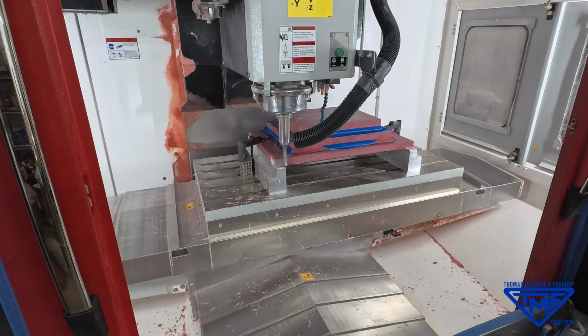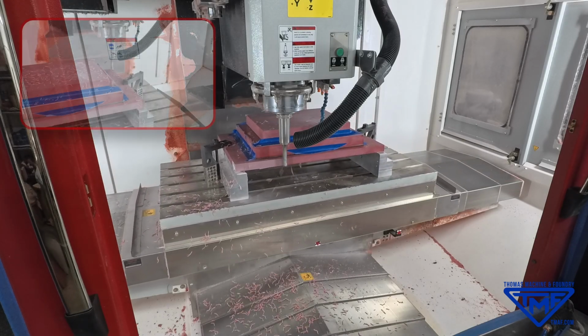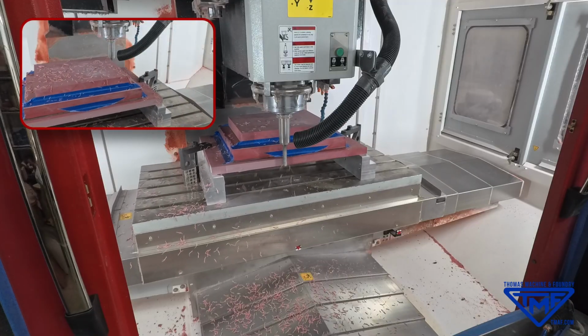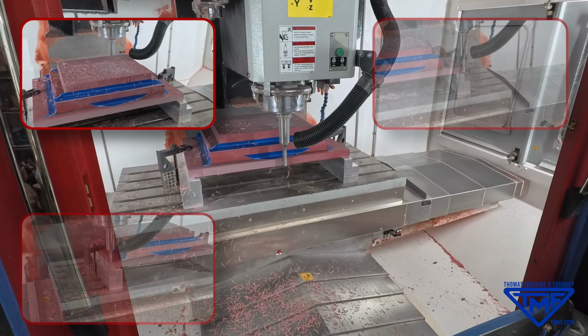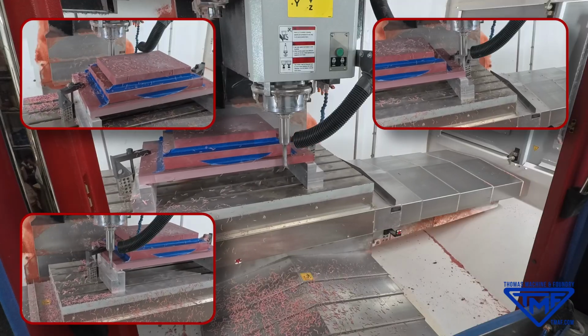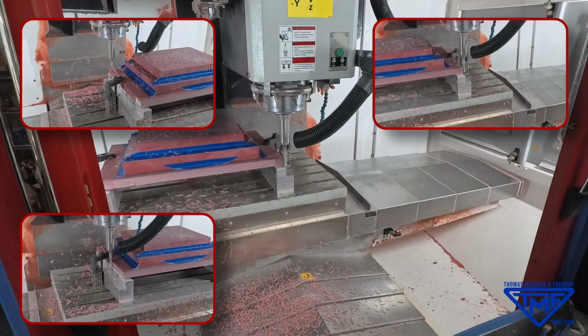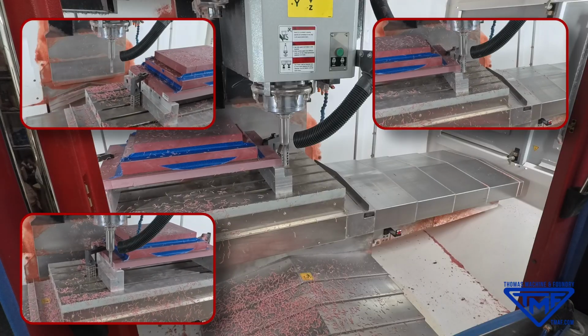The next step is creating these reference surfaces on the pattern itself. The front and rear edges are machined flat and precisely located. Then, the left and right edges are machined the same. These finished surfaces become permanent datums, or known starting points. They give us reliable reference points for future machining, inspection, or repairs.